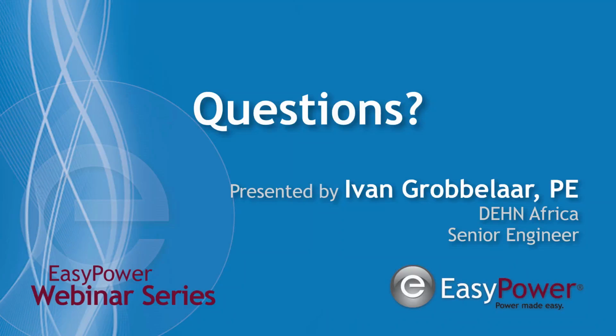There's another question regarding what specific resistance was considered during the calculation. I'm not sure what resistance this is referring to. Maybe if you can reach out to us with an email, that's something that I would really be interested in understanding and answering as well. I'm not sure if it's the grid resistance itself or any of the components. Oh, I see. Okay, so it was about the soil. Again, in this specific case, those were two different PV plants that we showed. In both, the one was in South Africa, which usually has a very high soil resistivity, so it was in the area of about 800 ohm meters, if I remember correctly.